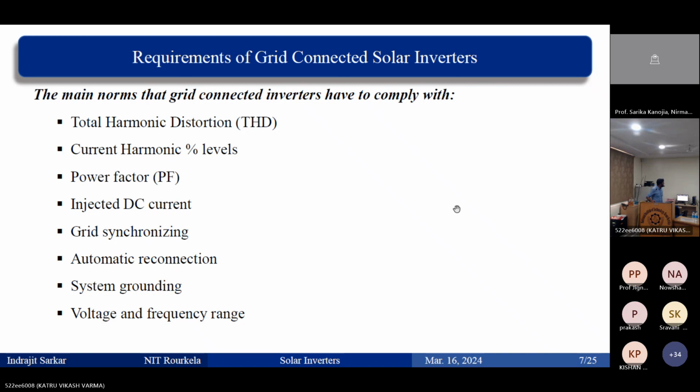We are not saying you make it zero, which is not possible at all, because that high frequency current harmonic is going to be injected anyhow. If it is a low order harmonic, it should be less than 1%. In simulation studies, I see reports where people present simulation results with lower order harmonics exceeding 1%, and they say, sir, THD is coming less. It is not like that. Your individual harmonic that you are injecting, apart from 50 Hertz, should be less than 1%.